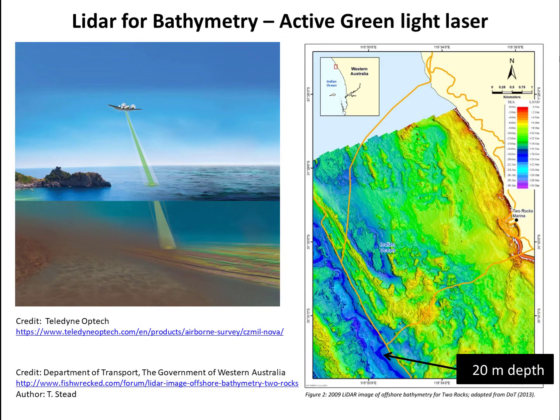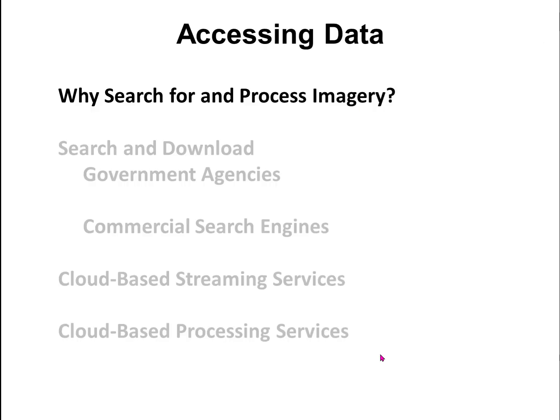And this is LiDAR for bathymetry. It uses a green light laser that penetrates the water. And you can see it's more complicated because it gets refracted when it hits the surface. But in the end, they've corrected for these in a remarkable bathymetry map with a water depth down to 20 meters. So let's move on to accessing data.